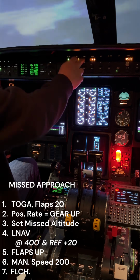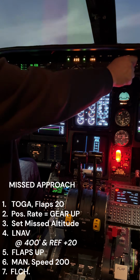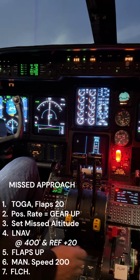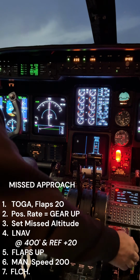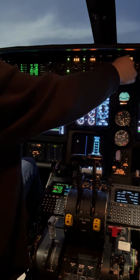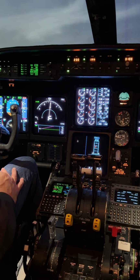We want to go back to LNAV. We're already in FMS, so we don't have to worry about that. Telling us to make that turn. And then flaps up, manual 200 and flight level change. And I'll fine tune the altitude here. And that's it.